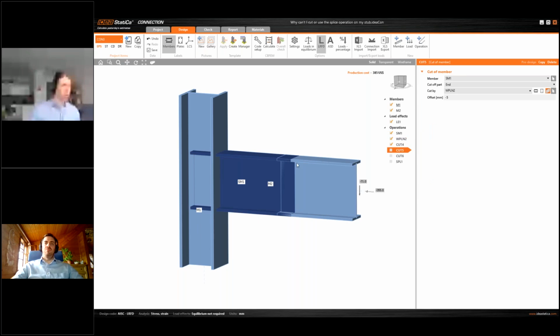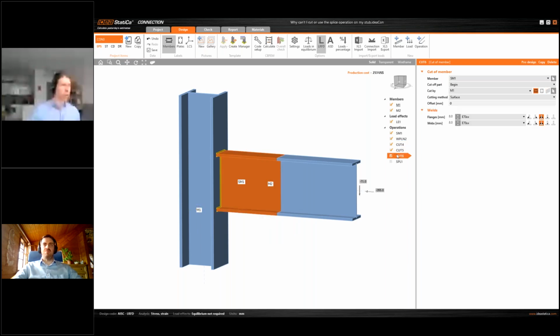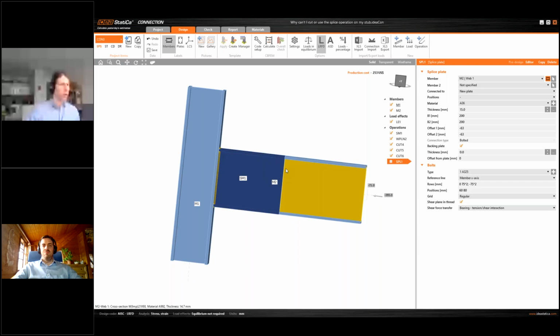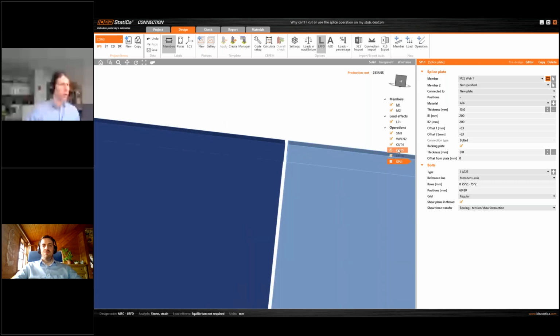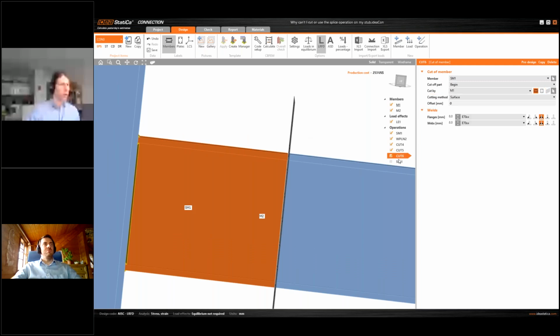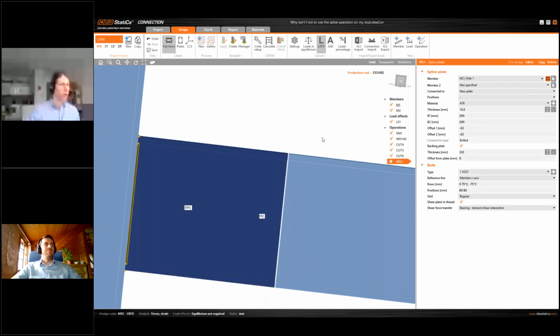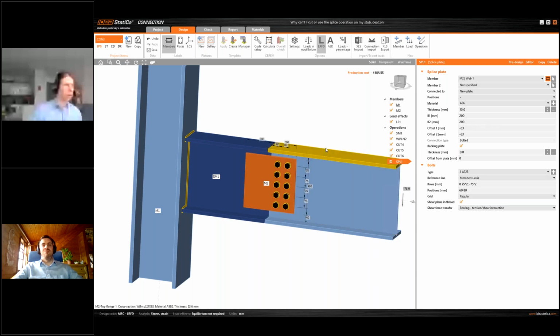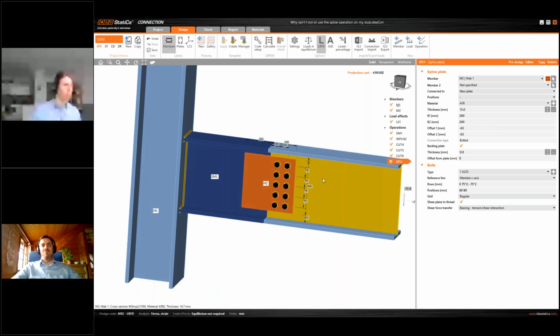So now I need to somehow cut this stub. So by this work plane, I will take advantage of what I already have, and the other end, just cut and weld. And the last thing, this is now looking okay. I have even a small hole in here. This is because for the cut of the stub by the work plane, I inputted -5 millimeters to produce this 5 millimeters hole.